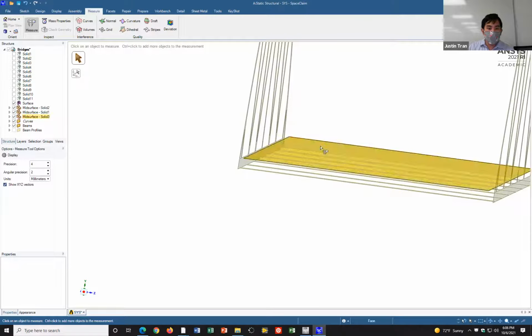And then we're going to click on the side of the bridge. Go ahead and hit apply. Okay, that did not connect what I wanted to. You want to make sure that you're connecting the side of the road. If you see right here, I've actually connected the bottom of the bridge surface with itself, and that's not right.